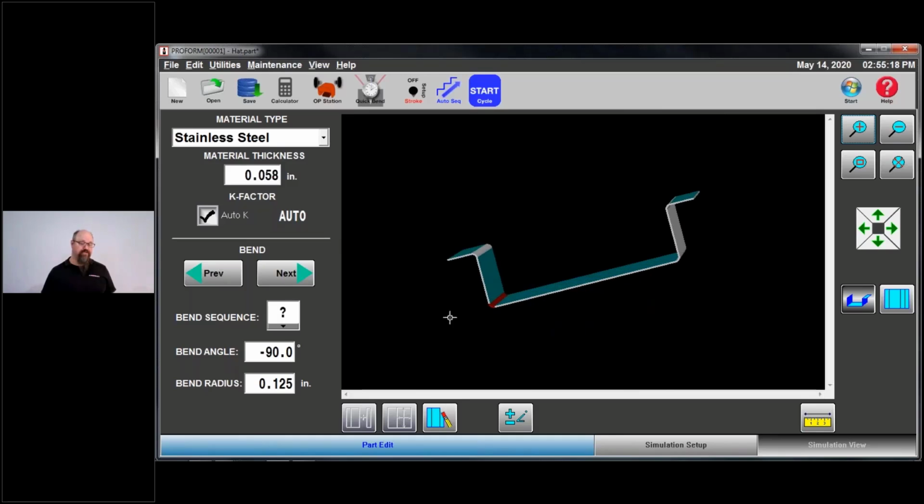Similar to what we did, except it's the same material but has a wider radius for whatever reason. We would be using that wider radius. So the IGES files are certainly cool, but I've had the most heartburn with IGES files. I've got about a 50% success rate with them. If you start getting issues with those IGES files, go back to your solid model, see if you can export to a sheet metal flat, and then bring in the sheet metal flat as a DXF or a DWG. Those are just generally my recommendations.